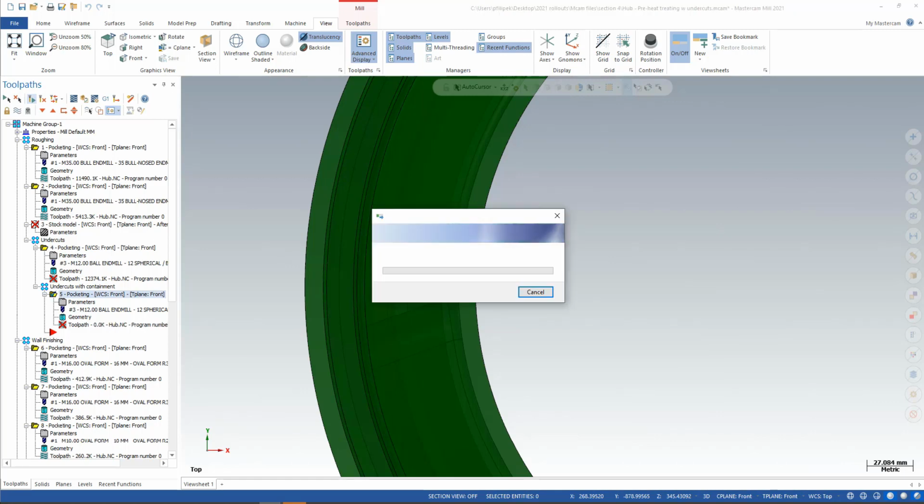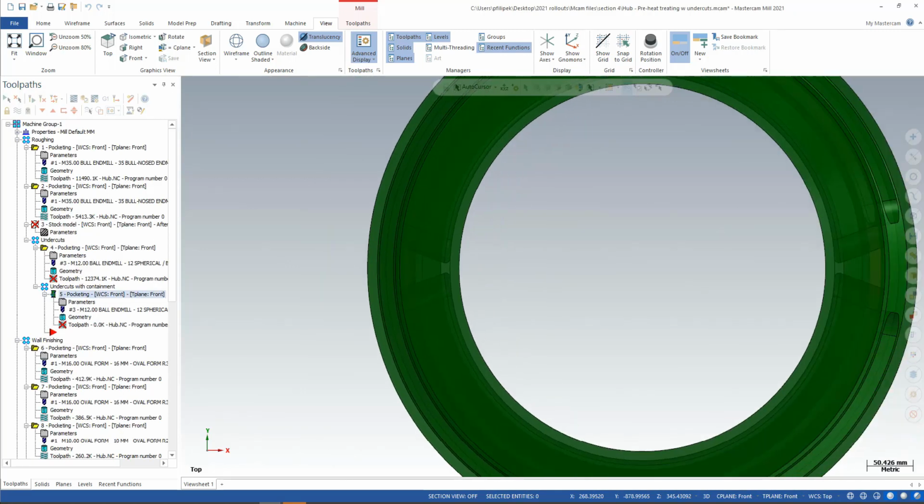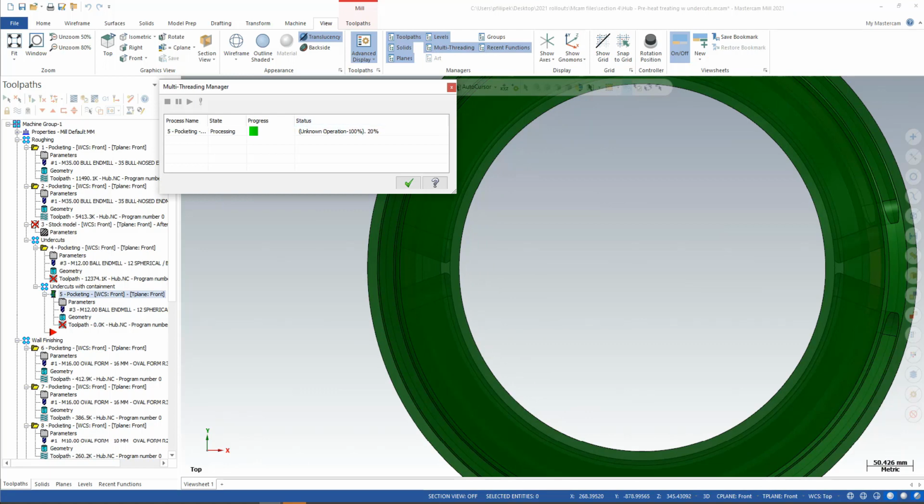And once again, these crunch pretty fast. Takes just a little bit here. And now this cut will only cut the undercuts for me. So I already have the whole pocket roughed out except for the undercuts. This will come and clean out the undercuts for me. It's a good process to get into: dynamically cut out what you can and come back and just do the undercuts. And this toolpath allows that.